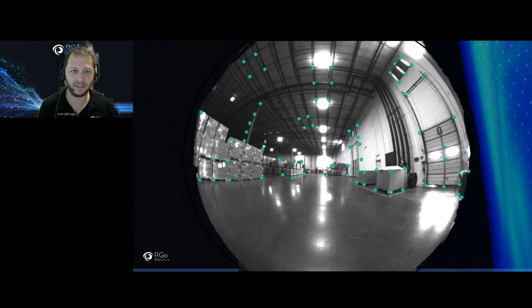How this magic works is a brilliant question that people ask me. Traditional vision systems sometimes look at the difference from frame to frame, trying to evaluate the changes between one frame and another. But as you all know, this will accumulate error every once in a while when you drive, and the best VSLAM system will tell you there is less than 0.5% error. But when you drive a kilometer, it's a huge one.